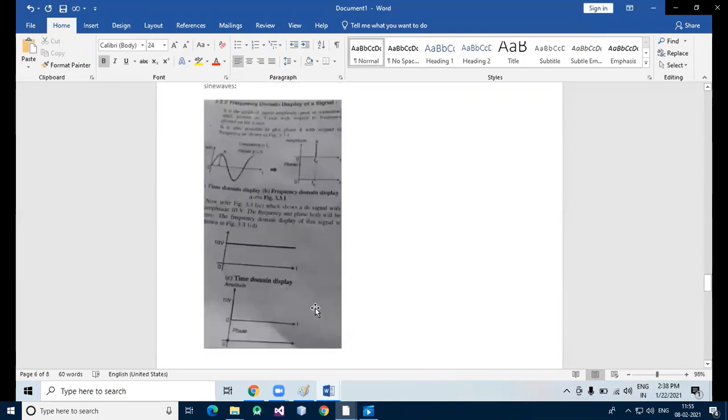It is a graph of signal amplitude, peak or sometimes power, plotted on the y-axis with respect to frequency plotted on the x-axis. It is also possible to plot phase with respect to frequency. So here you can see frequency is indicated by f0 and phase is indicated by t0. So this is the frequency, this is the amplitude and this is the phase.